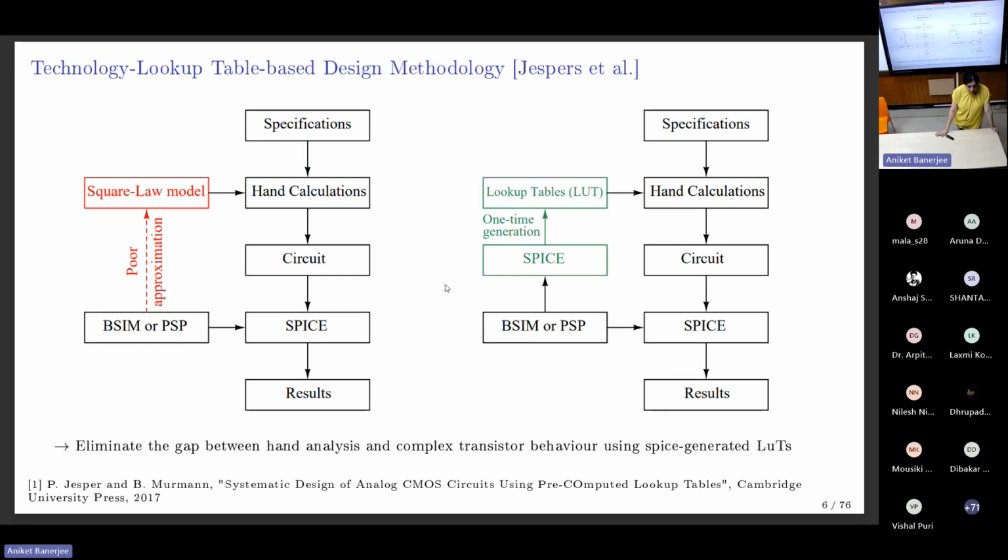The thing is, I remember designing circuits the first time around, and there will always be: what is the overdrive voltage, and then design backwards. You have to set some overdrive voltage and design backwards. The problem is there are rarely circuits where you get to choose overdrive voltage and say, okay, let me give 200 millivolt in the circuit. It doesn't work like that, right? You're sometimes feeding a current or bias current, or you bias on chip with a certain voltage. So this idea that overdrive voltage is where we need to start is coming from square law. So we let go of overdrive voltage with grace.